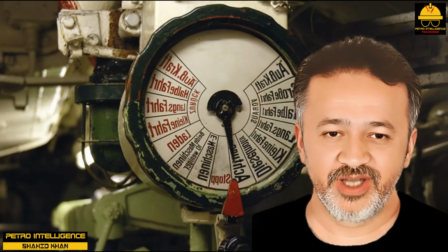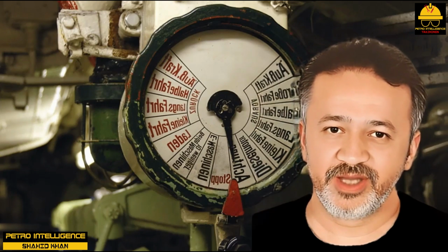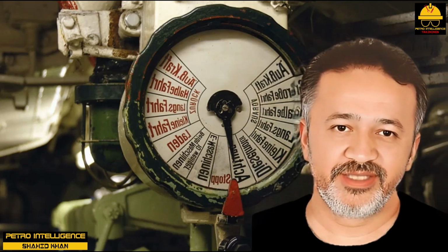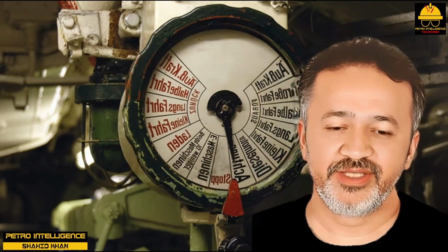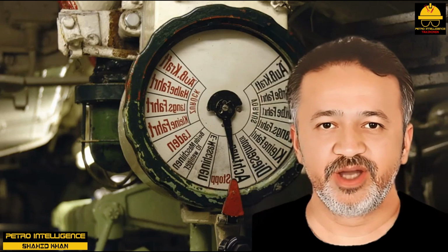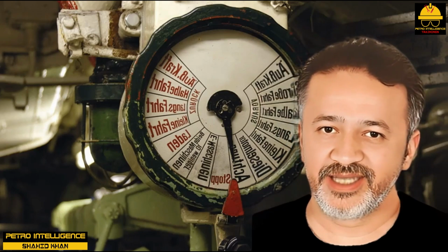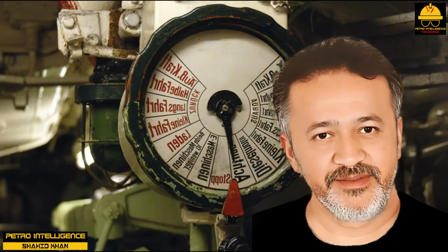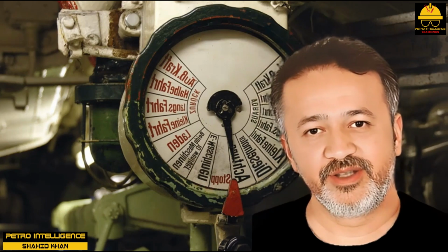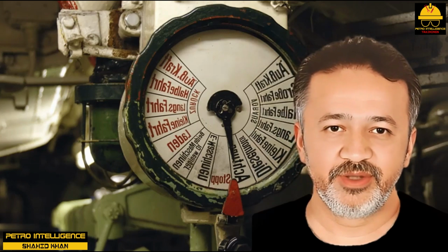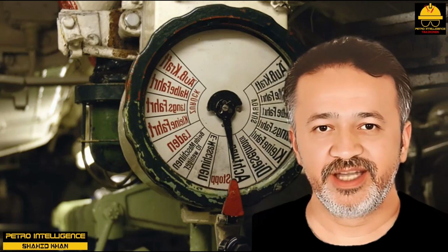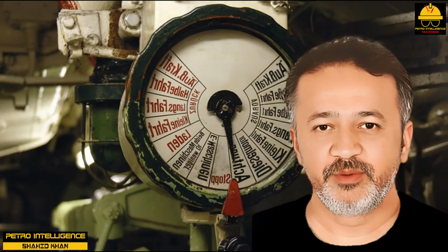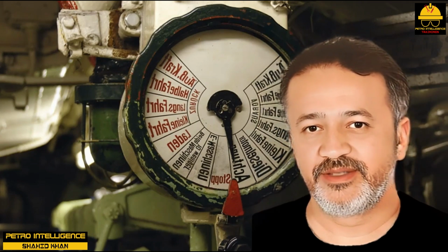Manual and automatic control. During a unit startup, console operators will use manual control to initially establish a steady state flow through the system. Typically, when a new process is being brought online, a control loop will swing high and low as it attempts to match the set point. Experienced technicians are familiar with the operating valve percentage that is established when a unit is lined out. By placing the valve in manual control, process variations are reduced.